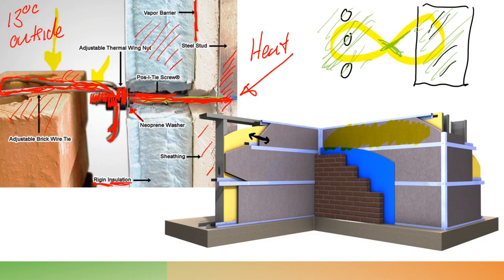So it's a well thought out system where even the brick ties are fixed through to the rigid insulation system. Remember the brick ties up here. If heat does travel along the brick tie, it's going to stop at the insulation there. It's not going to pass through. A very rigid system in terms of thermal bridging, but likewise it could be costly as well, could be expensive.